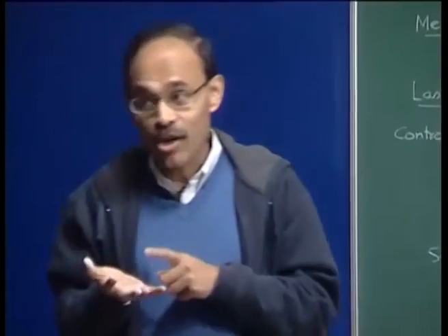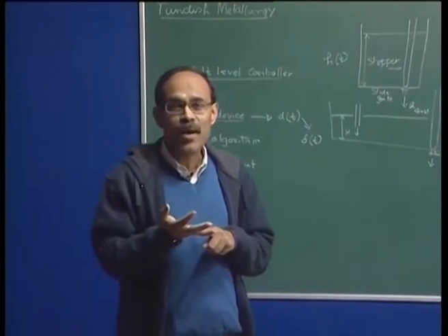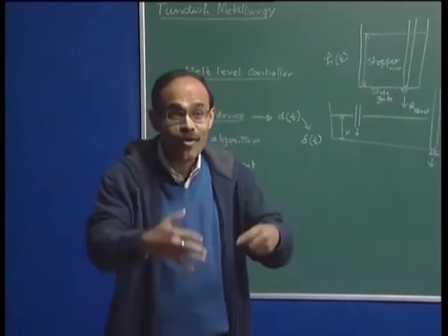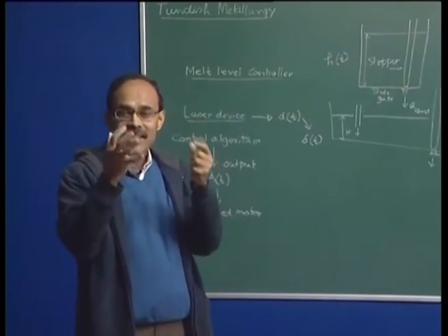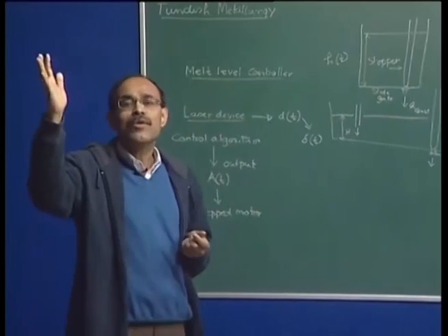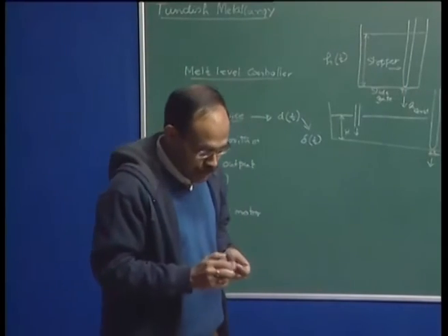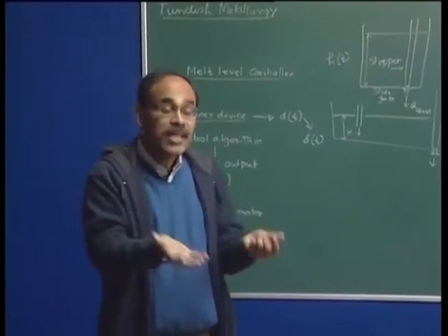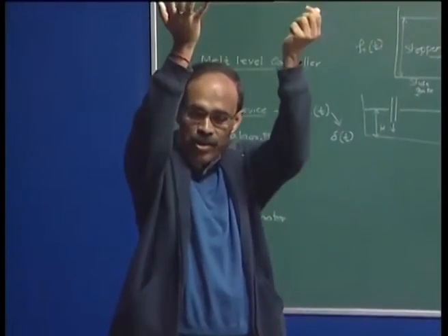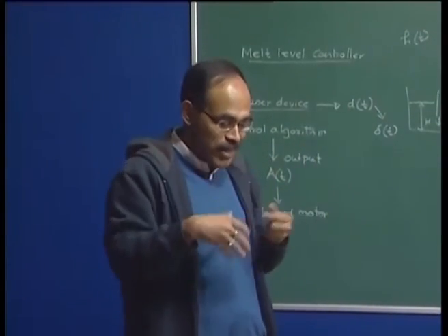First, we have seen deoxidation, and then subsequent to the deoxidation we have talked about inert gas purging, and I have already mentioned to you that inert gas purging is very important because we would like to now create stirring in the process. So, all along one thing in secondary metallurgy is central, and that is the inert gas stirring. All through the duration of secondary steel making we will have gases injected from the bottom, either one or two porous plugs. Now, following inert gas stirring we can go for arcing process where we can increase the temperature, which is the ladle furnace, which increases the temperature of the bath. We can also do alloy addition and compensate for heat loss and alloying, etc., through the arcing.